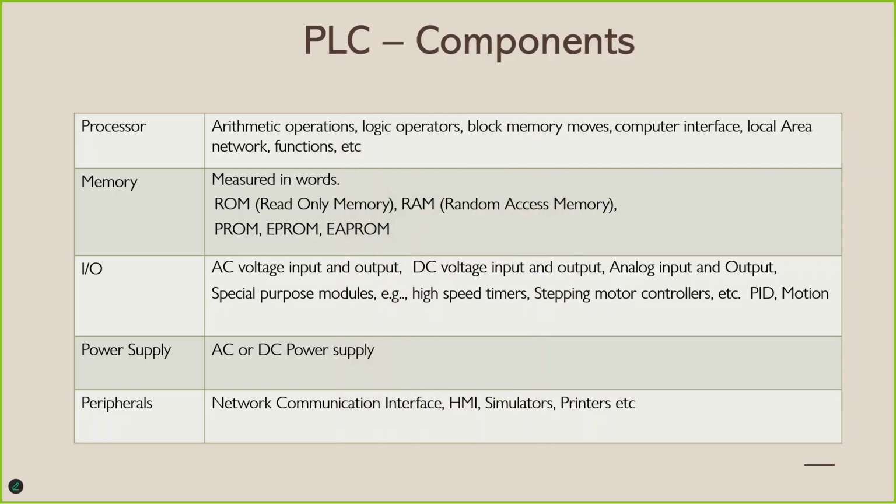Here we'll talk about PLC components. The first part, and this is not according to order, so I'll just go irrespective of the order: power supply. A PLC can have AC or DC power supply. I've mentioned earlier, some PLCs have their power supplies embedded on them. You just need to go in with the cable, either AC or DC supply. And some PLCs have external power supplies.